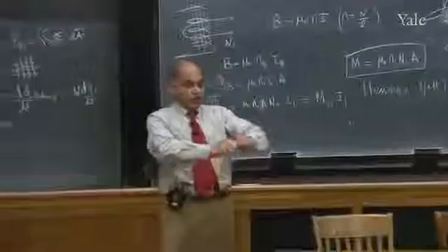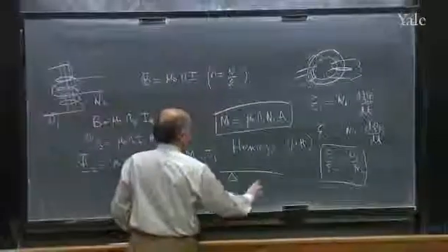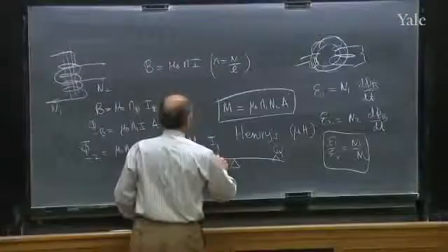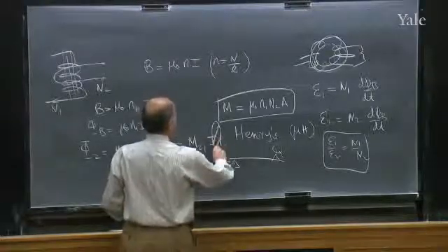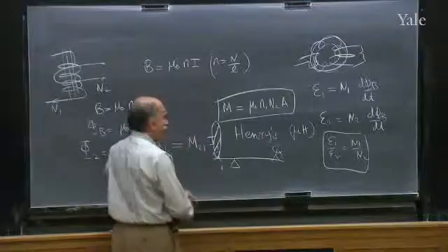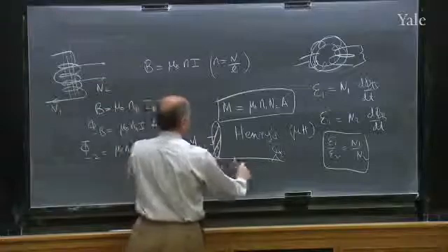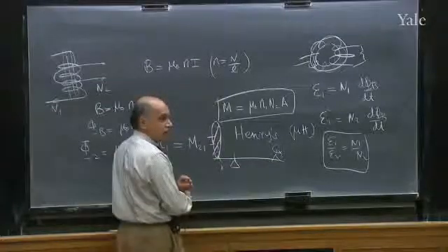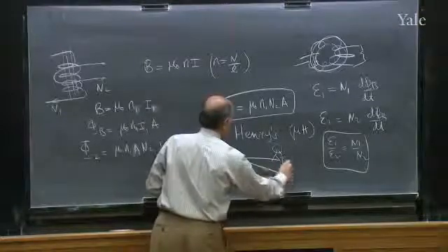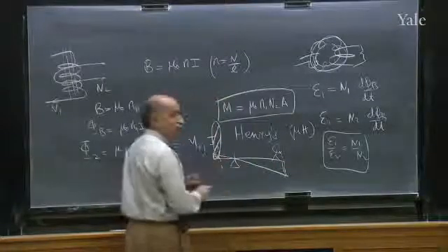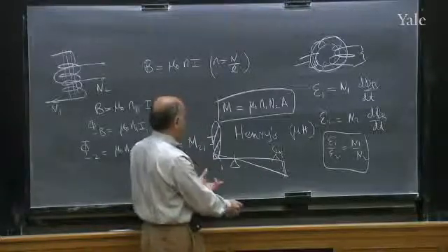It's like a lever. You have a long thing, and you're trying to lift some object here, and you are trying to lift with a, I got it backwards now. So this is a huge object. It's a tiny object. You can balance them. By varying the distance, you can have a tiny guy lifting a big one in the inverse ratio of the distances. But you don't get any free mileage out of this, because if you look at the work done by similar triangles, this will have to move a lot, that'll have to move a little. So the work done is the same, but it doesn't mean it's useless, because this is the only way you can lift something very heavy.